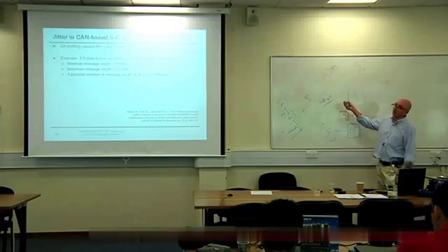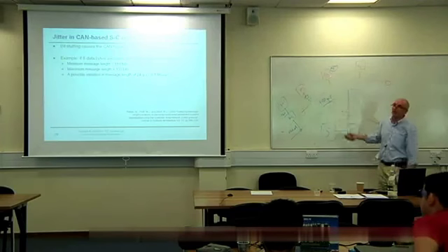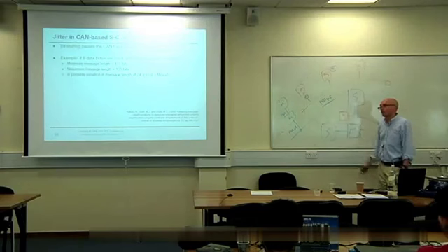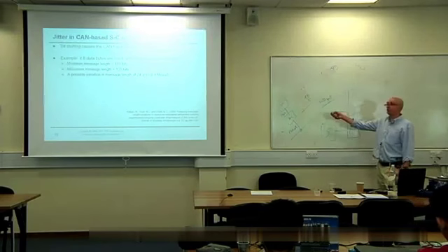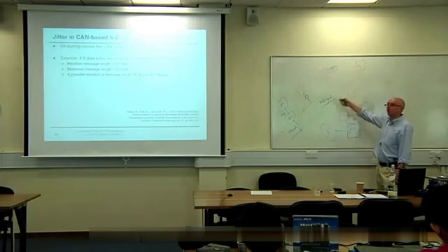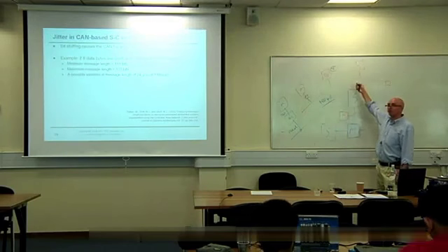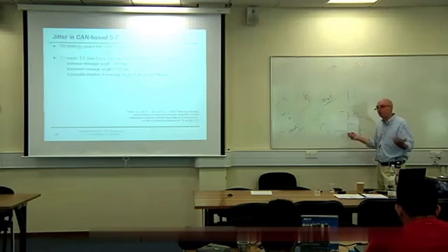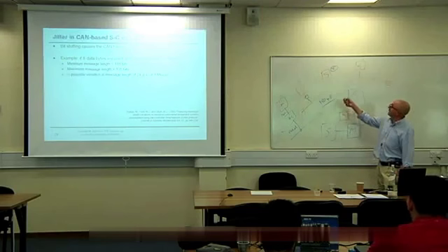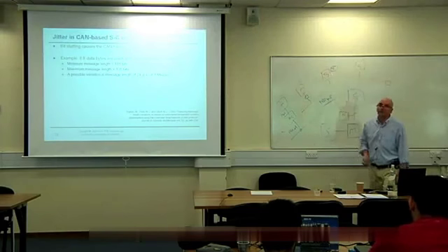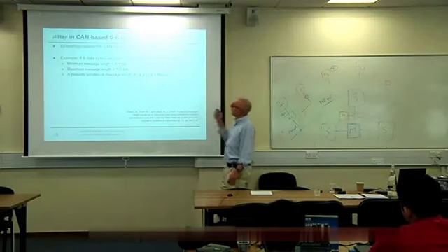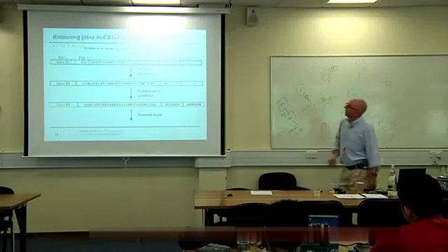If this node is doing our data sampling, well, for a start, which one to use for data sampling? This one. Sometimes people think if it's a control node, this one should be doing the controlling, that one should be doing the data actuation, that one should be doing the data sampling, that one should be doing the control. Because obviously the master node should be doing the control, sometimes the way people think about it. It doesn't work. If that's doing the data sampling, you might have a significant level of jitter in the data sample times.